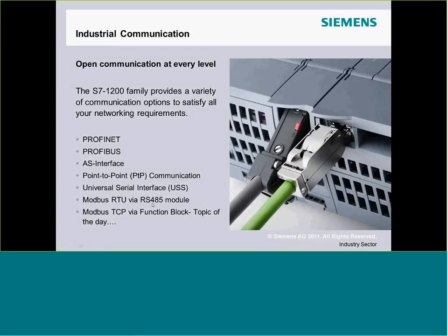Then we have Modbus RTU, which is the RS-485 module or the RS-232 module. And then the topic today is ModbusTCP. We are going to write a function block, pass some parameters to the block, and see how easy ModbusTCP communication is via the TIA Portal software.